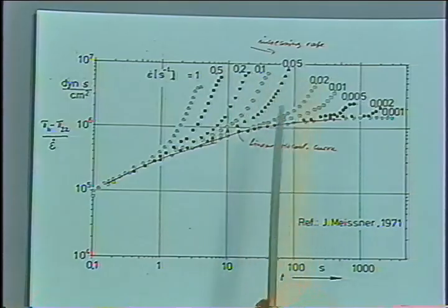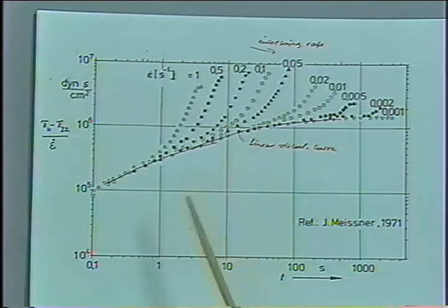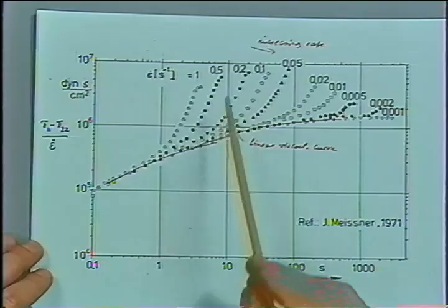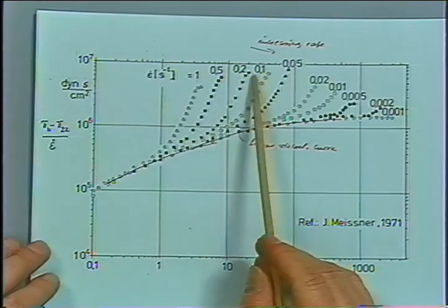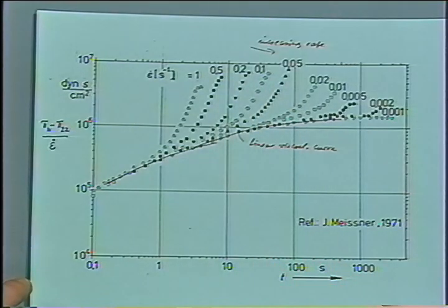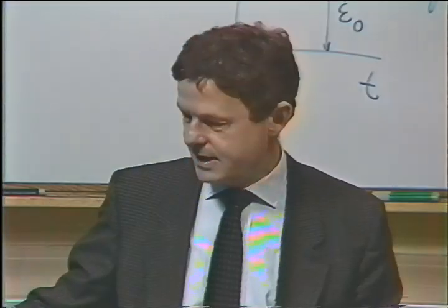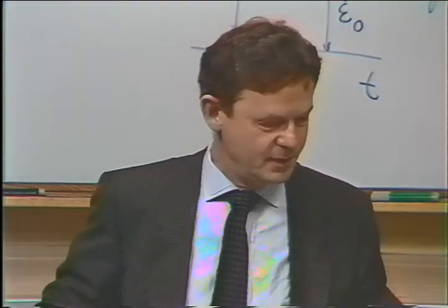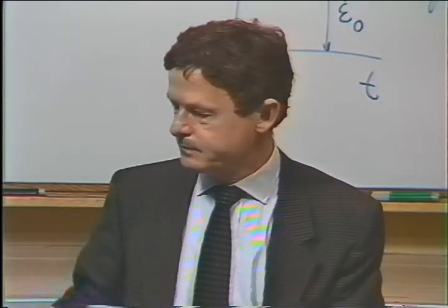So it's a question of long disputes. What will happen at high values of deformation at very long times in extensional flow? While in shear flow, it's settled. There are lots of data, and we know that we can use steady shear behavior, and everything is fine.